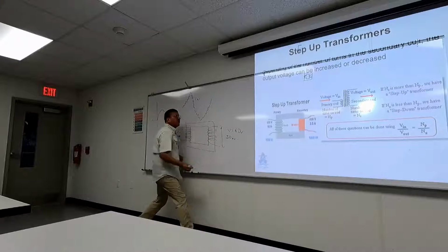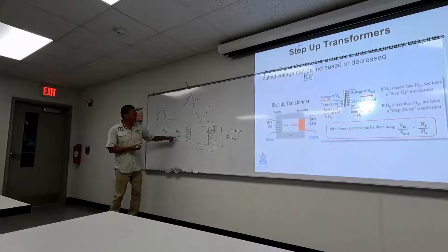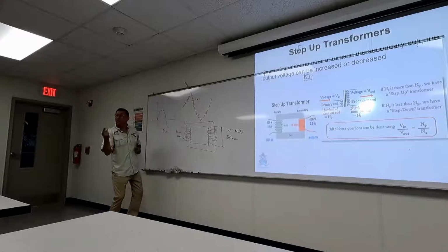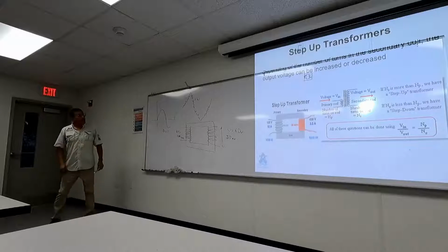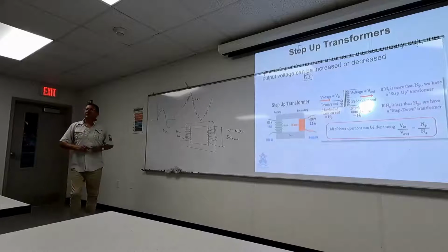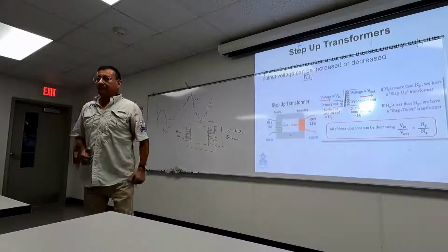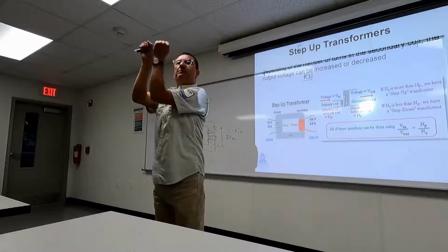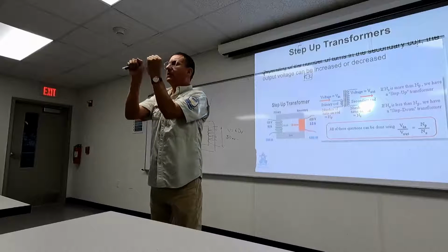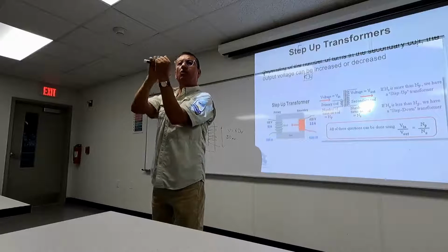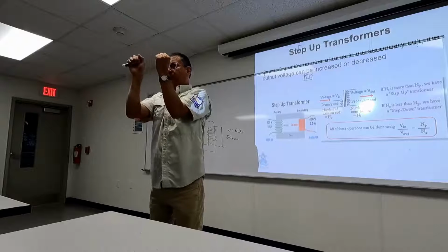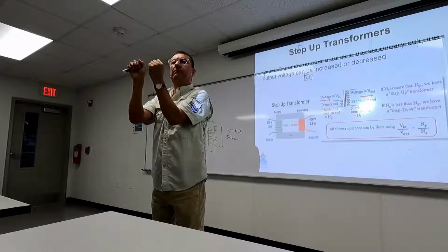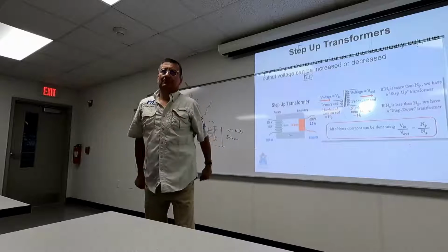Is 60 volts, because I have half the turns. All right. The formula is this. What is the secret in a transformer? What happens with the power at the input with respect to the power at the output? Should the power at the output be higher or lower than the input power? Or should it be the same? Lower voltage. Always the same.